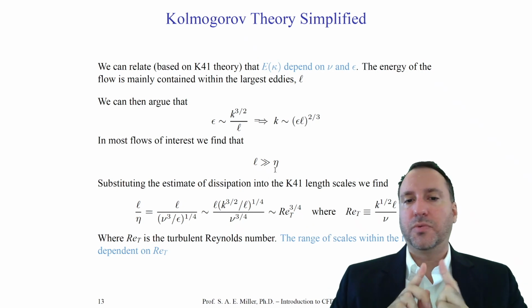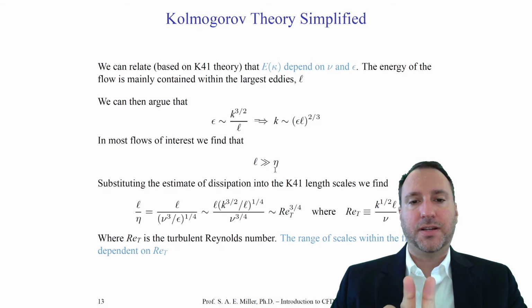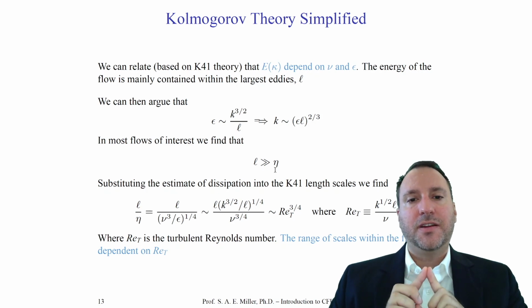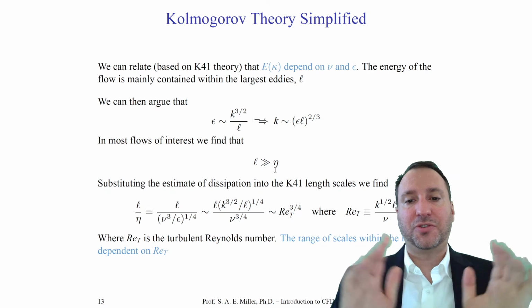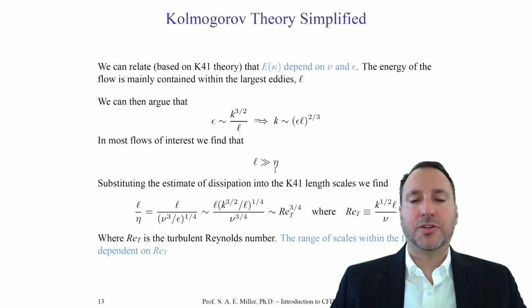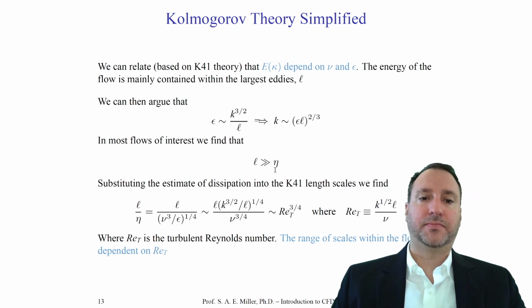So if you just take a ruler, perhaps naively, and measure a vortex at the small scale, you'll need a huge ruler and a different ruler to measure the eddy at a larger scale. In the turbulent atmosphere, you have length scales which can be kilometers in size or larger, and you have Kolmogorov scales, which are on the order of centimeters or smaller, just as an example. And this one's not a very high Reynolds number.